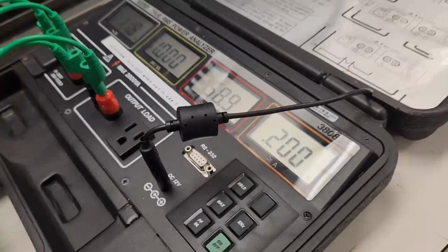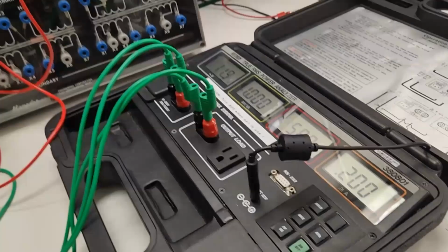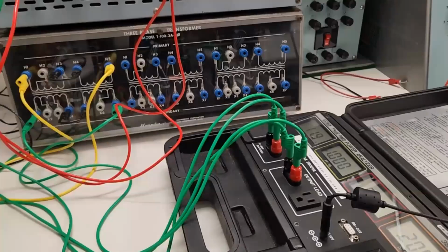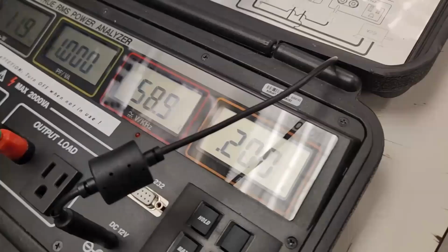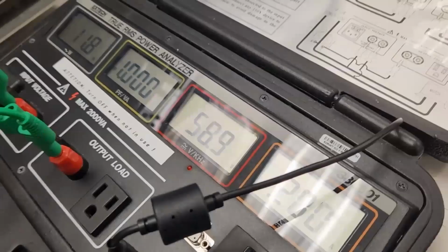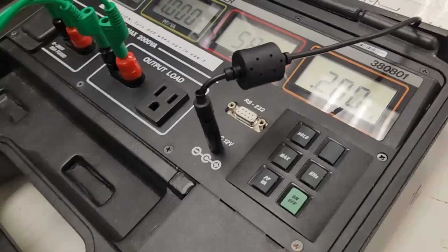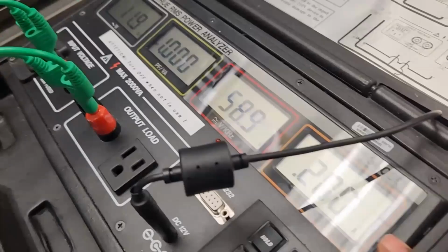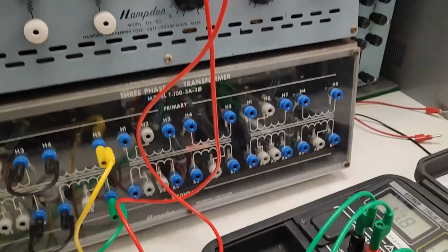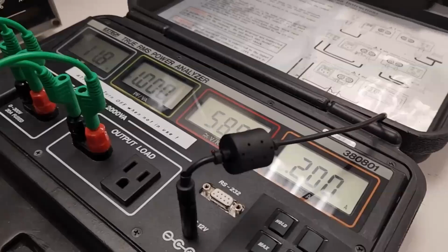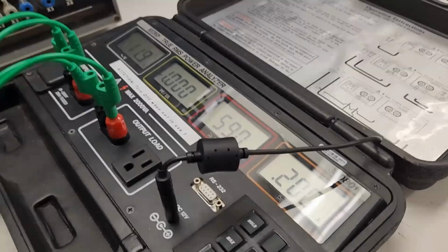The current is 0.2, but in order to calculate the voltage regulation we will compare the output voltage, so the current has to be equal to the current that we measured for R. Now the current is 0.2, which is a bit larger, so we'll have to adjust the loads to get the current to 0.17.